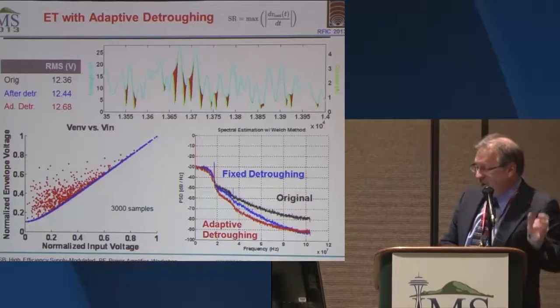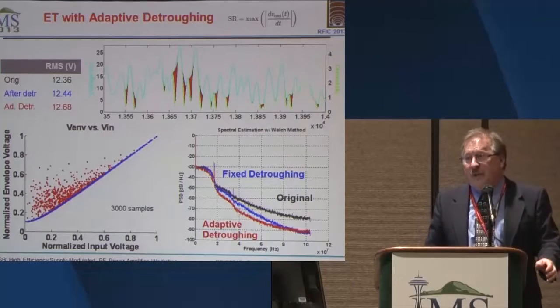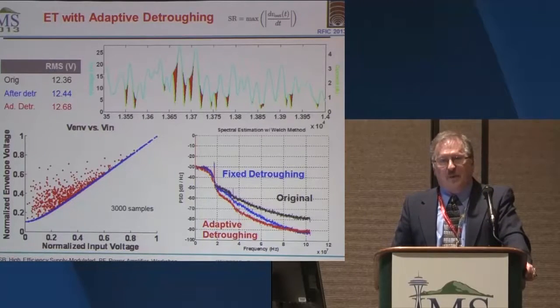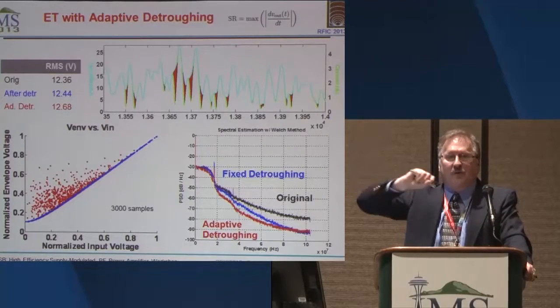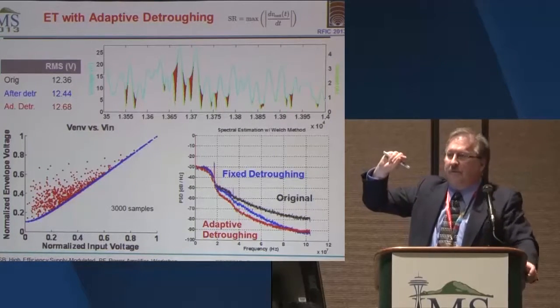So for wide modulation bandwidths, this is where some of the more exotic DPD schemes are kicking in at this point in time. And that is when I don't follow this one-to-one relationship between the VD and the VN. If for the sake of the envelope amplifier, I'm reducing the slew rate or reducing the bandwidth, modifying that envelope signal, I may want to do that to help the bandwidth or performance of the envelope amplifier.